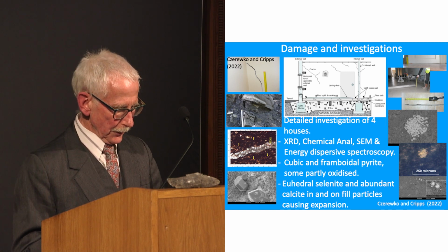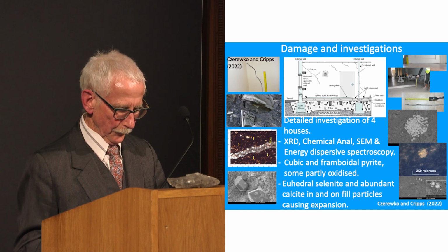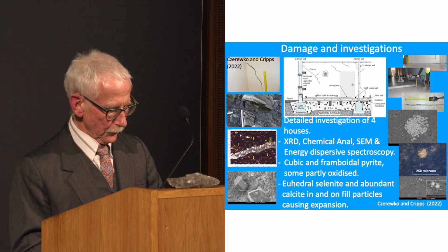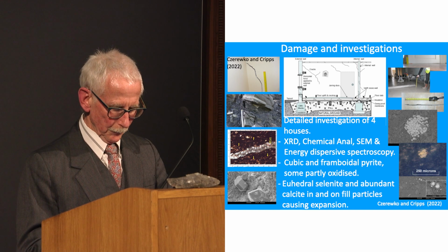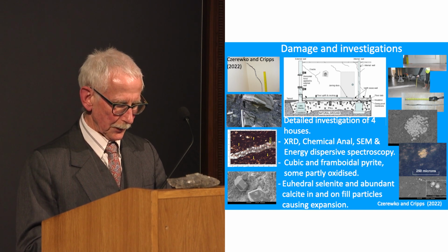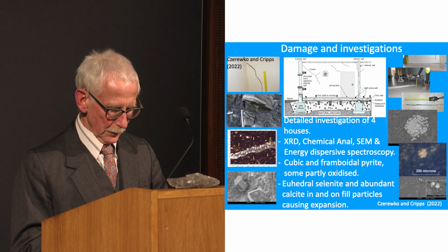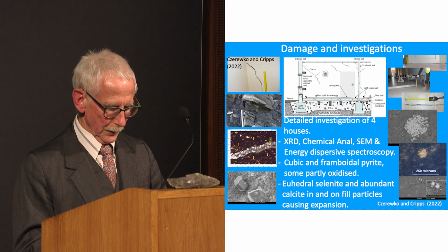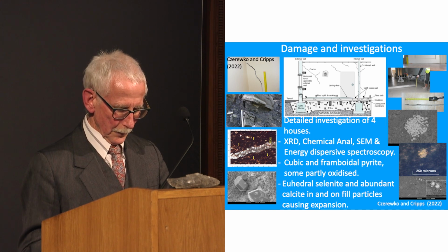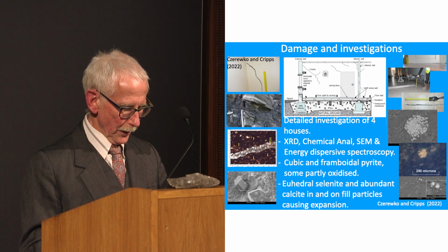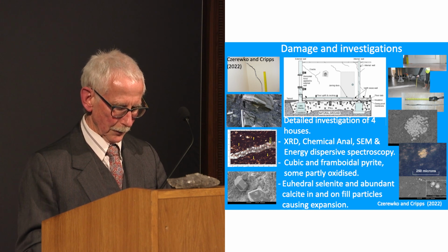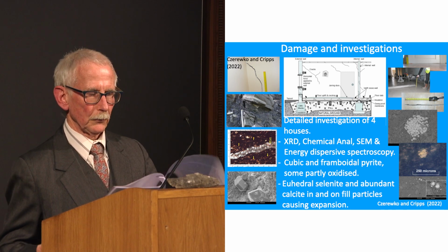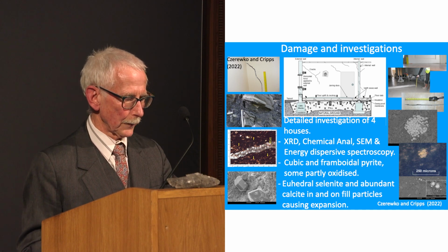The expansion of the selenite would create cracks in the fill and provide pathways for water and air. Some people had argued that the growth of selenite would have filled pore space in the fill before causing expansion, but the growth of existing crystals in cracks requires lower surface energy than creating new ones in a void, even if this is against a confining pressure. Therefore, the formation of these selenite crystals widens cracks in the mudstones, causing them to expand. And this is greater if the particles are weak or laminated, which they are in this case. It's a weak mudstone.